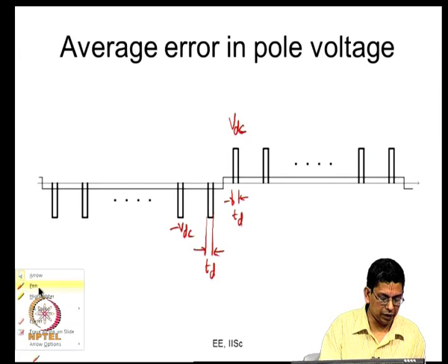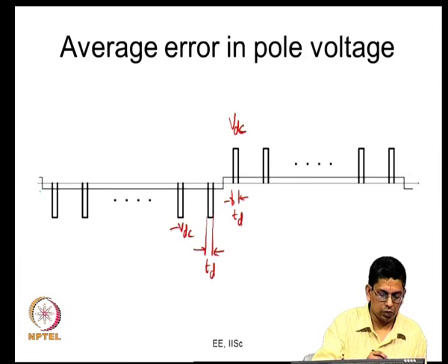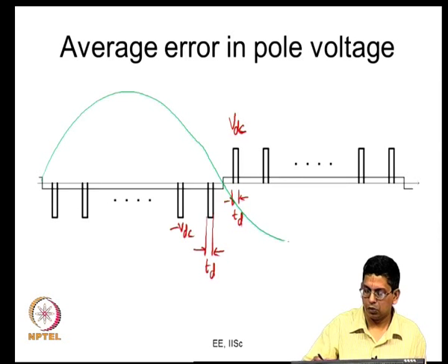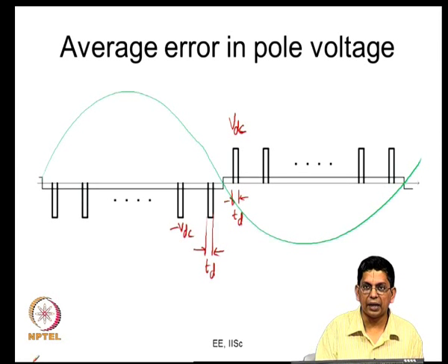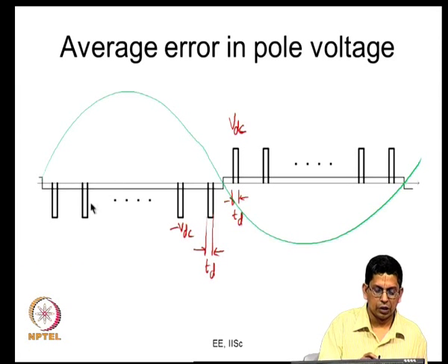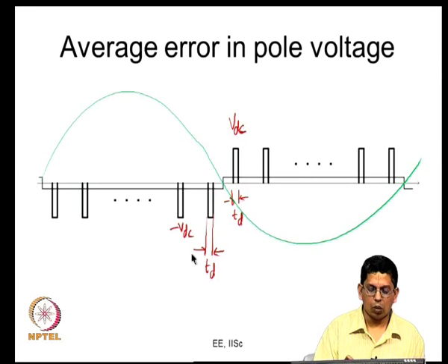So, in fact, you really have your line current flowing like this. Okay. So, it is periodic, and what are the frequency components it will have? It certainly has the fundamental component. Let us say the fundamental frequency is 50 hertz. So, what all components will this error pulse waveform have? It will have 50 hertz, 150 hertz, 250, 350, 450, 550, everything. It will have all the odd harmonics, because it is roughly half wave symmetric. So, the even harmonics might not be there, and all the odd harmonics you are going to expect there.